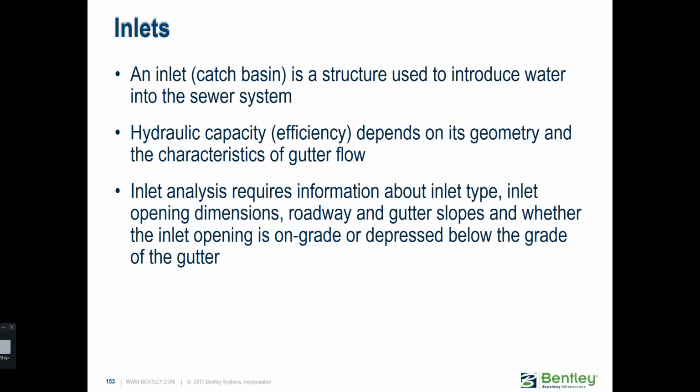All right, so an inlet, or also called catch basin in the software, is the structure where we let the water into the underground sewer system. Its hydraulic capacity or efficiency depends on the physical characteristics of that element and also the flow in that gutter. In order to analyze inlets, we need to know what kind of inlet it is, what are its opening dimensions, what is the road slope, what is the gutter slope, and whether it's on grade or in sag as we had been modeling them.